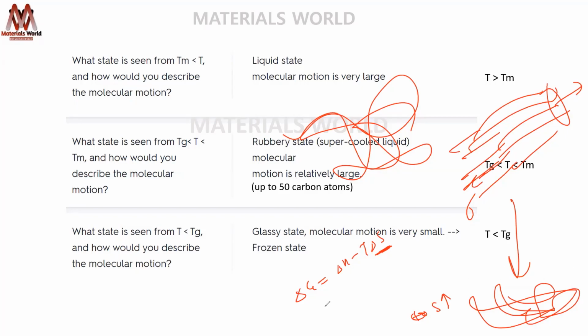Now, what about the heat? Heat will be minimized so that delta G will be negative, by dissipating heat. Like when you stress something, it becomes hot, and with time it becomes cold. Why? Because its molecules try to relax again to take a greater entropy configuration, and it dissipates the heat.